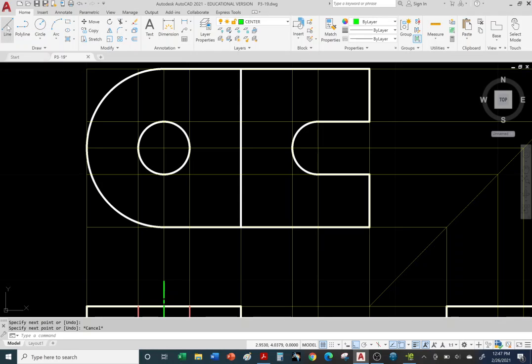Okay, so center line. Okay, so extend beyond the circle. See, it's trying to snap. Okay, so let me turn off object snap. I'm going to show you some other ways later on. I just don't want to overwhelm you with too much information right now. Okay, hit escape. Okay, and center line. Turn on object snap again. And see, it's trying to snap, so I'll turn off object snap temporarily. There it is. Hit escape to exit. Okay, so we got that done.